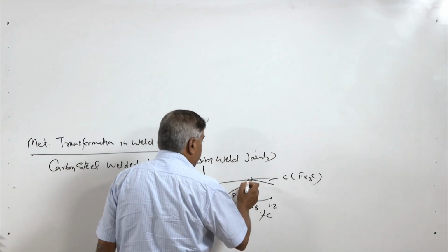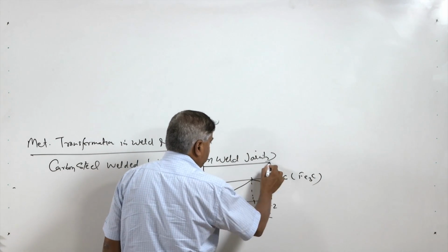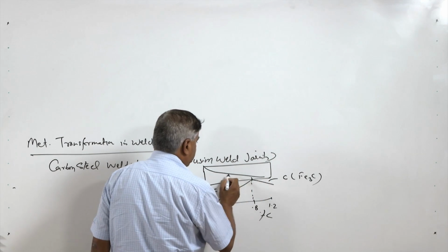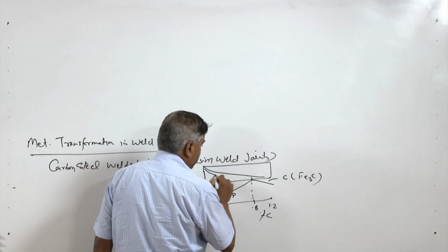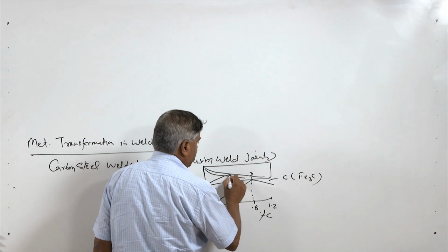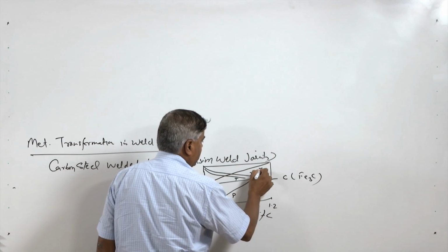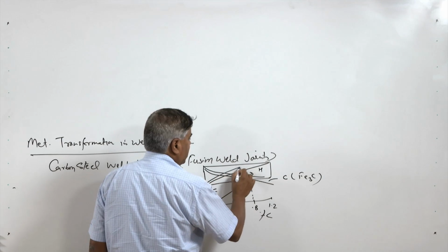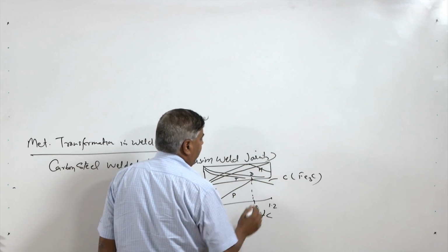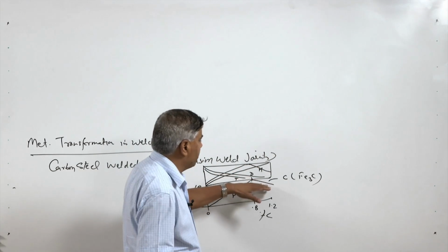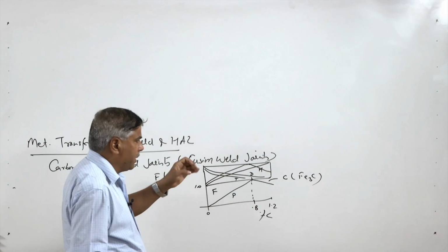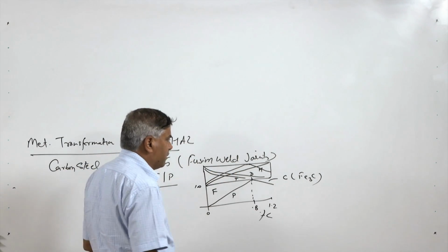This change in properties can also be shown schematically like this: there is a continuous drop in the strength, toughness and ductility. There is a continuous increase in the hardness, while the tensile strength increases up to the eutectoid point and thereafter starts decreasing, and this decrease is attributed to the formation of the cementite along the boundary of the pearlite, that is the pro-eutectoid phase which is formed along the grain boundaries.